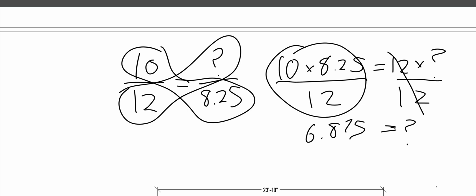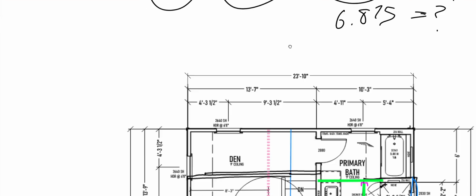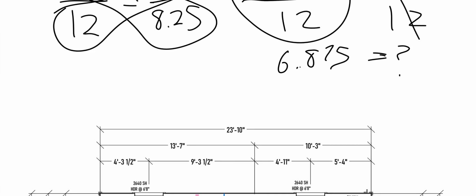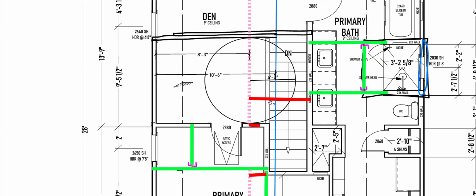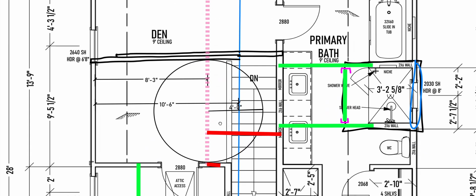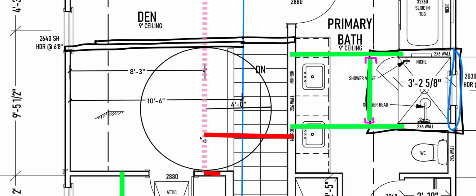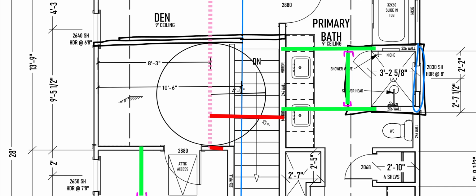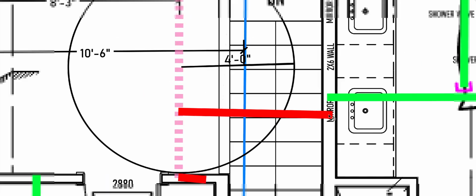All right, so we gained 6.875 feet as we went up, but we're going to lose a little bit of height from the purlin. Let's give ourselves some wiggle room here. Let's say we have 6 feet of clearance. If we have 6 feet of clearance, that means we have 6 feet of horizontal run. Well, actually, here's the trick. That would mean we have 6 feet of horizontal run. However, do we actually have 6 feet of clearance above the 9-foot wall?